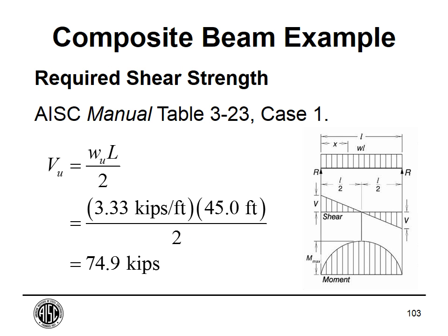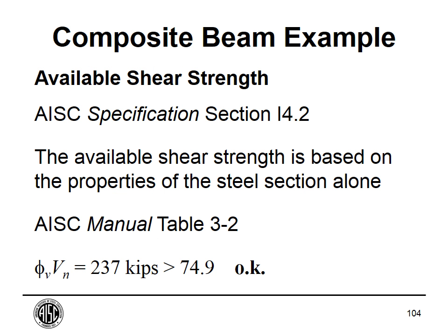Next up, I'm not going to go into detail on this. This is just the shear strength of the beam, and I just added it in for completeness. The same calc as in the example problem, with the exception of the live load is increased. You're just using the steel cross section, and the end of the beam is the location of the maximum moment, so we don't have reinforcement there anyway. We're going to solve for that in just a minute, the distance to the theoretical cutoff location. So we end up that our shear strength is good by a large margin.